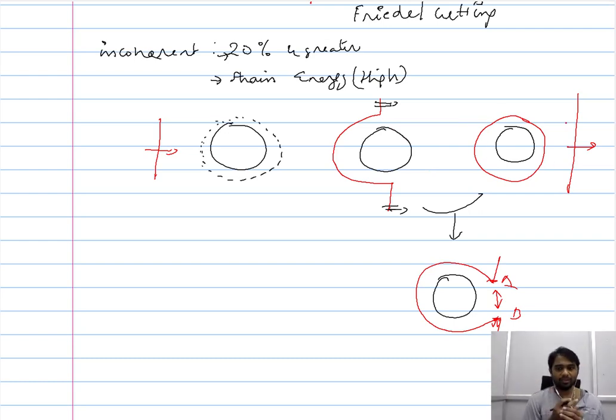So again, the dislocation changes its path. Even though we don't have a definite strain energy interaction or elastic interaction, we change the path of the dislocation, and we also need to have a detachment action here in order to separate this particular loop from the propagating dislocation line. So when a dislocation meets an incoherent precipitate, it propagates in such a way that it leaves behind a loop.